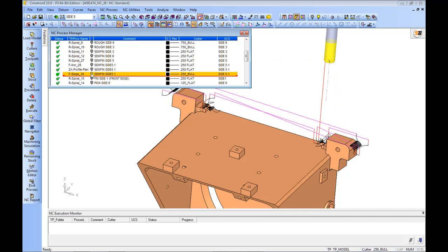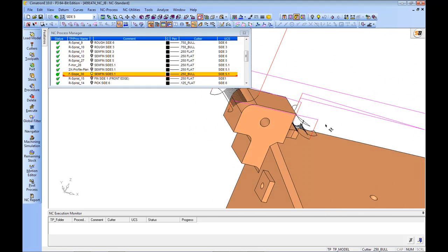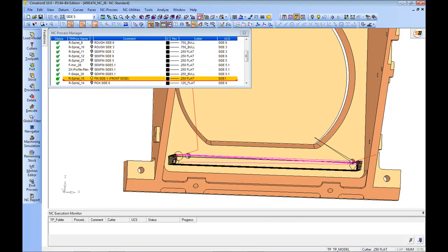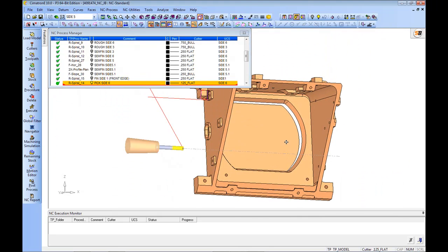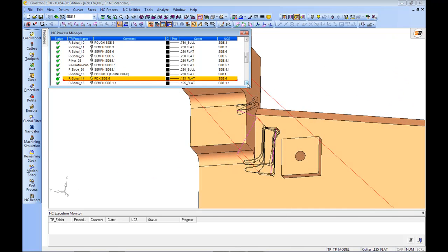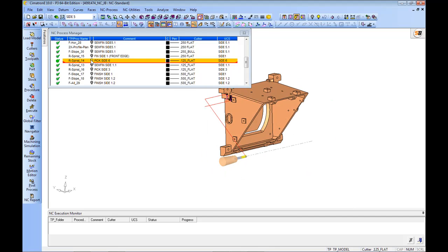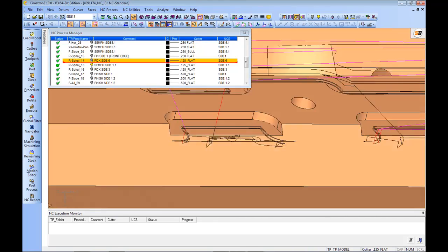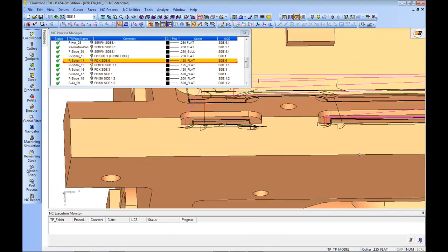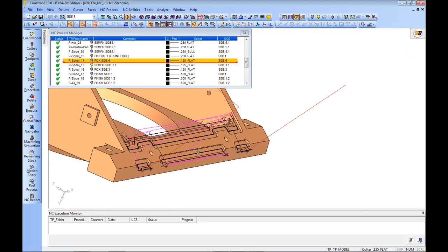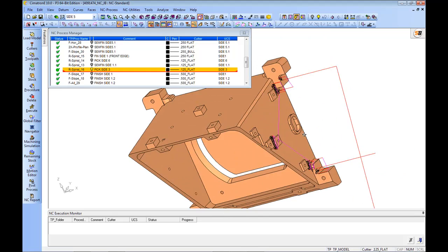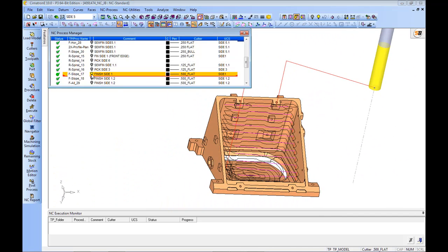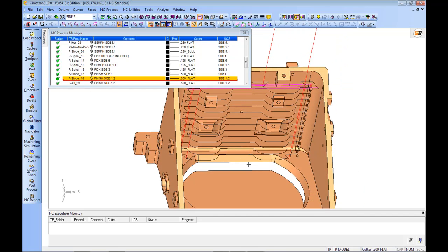The walls, establishing the rounds and the chamfers. Roughing down in here. Pick with a 1/8 inch flat. Oops. The finish procedure here again. Nice roughing motions, nice finish motions. Not a lot of material coming out of these areas. Another remachine. Finish with a 1/2 inch flat. Finish with a 1/2 inch flat on the appropriate tip for the back wall.